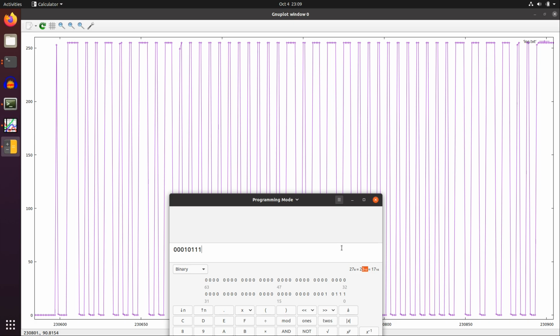That means we had 23 plus 37, which comes to 60, and binary-wise, it starts with 2 zeros, then 4 ones, and 2 zeros again. 1, 2, 3, 4, 5, 6, 7, 8. This belongs to the temperature. 1, 0, 1, 0. These are these two zeros. Then 4 ones, 1, 2, 3, 4, and 2 zeros. And then the line idles high again. And that's how it works.